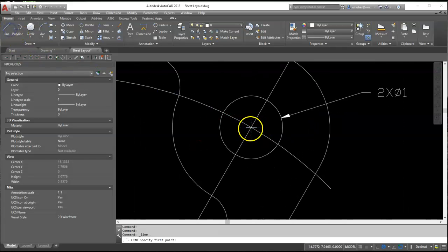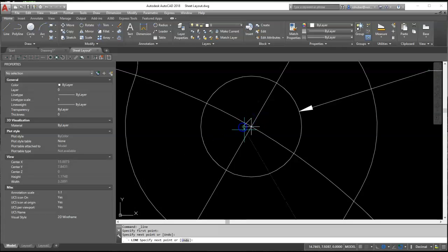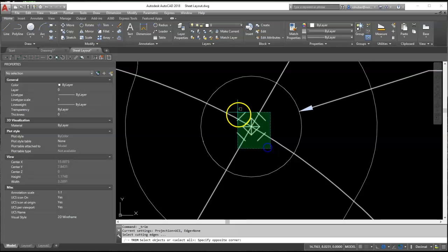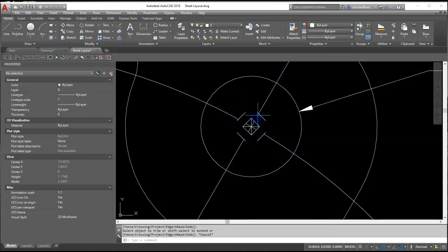Let's go ahead and box this. Now the sizing probably is not precise, but this is the best way to do this on the fly here. So let's go ahead and offset. Let's offset 1/16 of an inch, 0.0625. And that'll give us our trim boundary. Select everything, just trim this out. Go to delete. Just delete these lines out of here now. Delete our box.